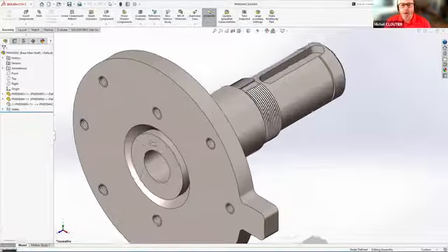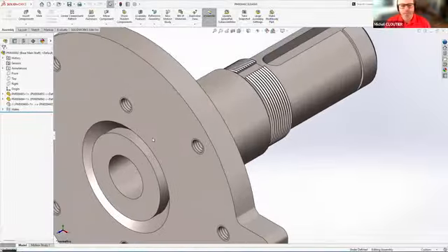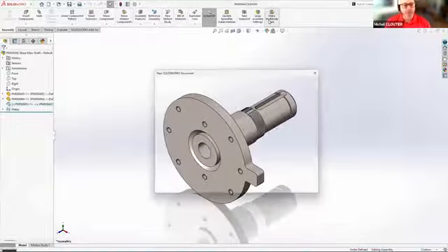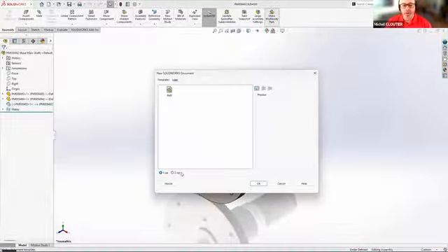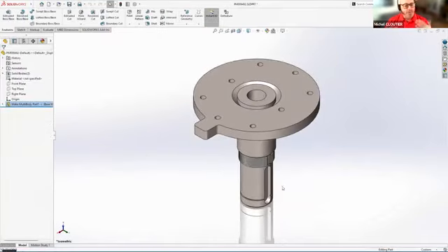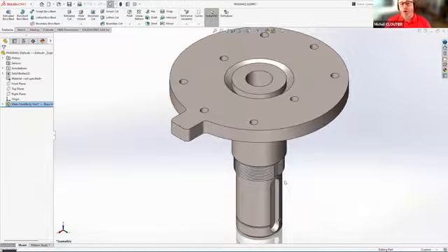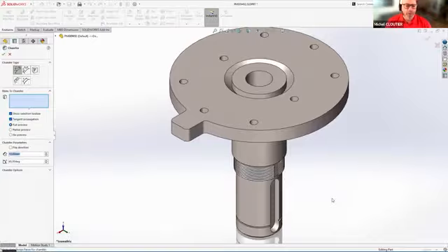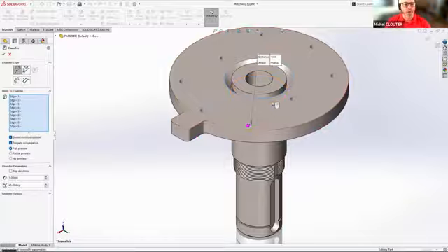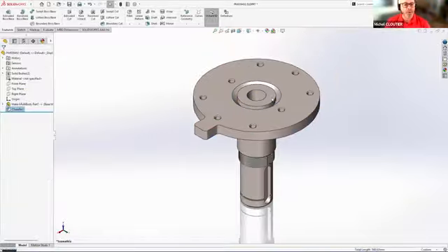So here's a fairly small assembly. It's a three-part assembly. And rather than having that as an assembly, I'd rather have that as a multi-body part. So in 25, we can simply say, go ahead and save that as a multi-body part. And you'll notice we now have Z-up templates, which aligns the orientation, but also all the planes for Z-up. Using my chamfer tool, I now have accelerators. You might have seen those on fillets, but now we're implementing those accelerators on chamfers as well.